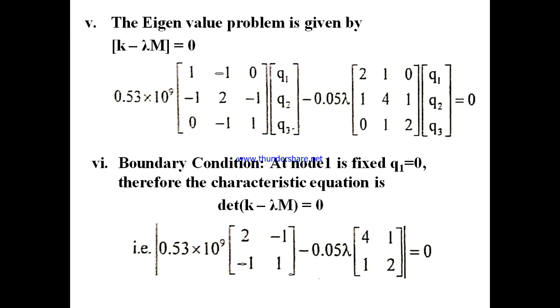So why do we require the natural frequency? In vibrations, in dynamic analysis, the vibration of a component is very important, meaning at what frequency it is vibrating. Once we know the natural frequency of a particular component, we can easily design that component. So the eigenvalues are very, very important. These eigenvalues will give us the natural frequency. So today we are going to solve for the natural frequencies also.